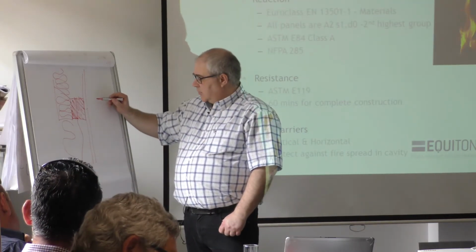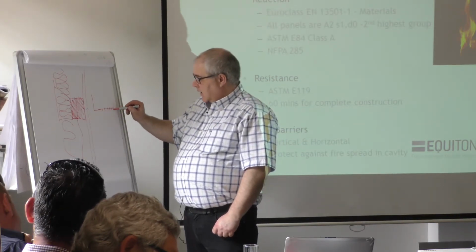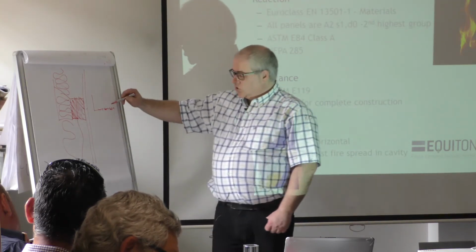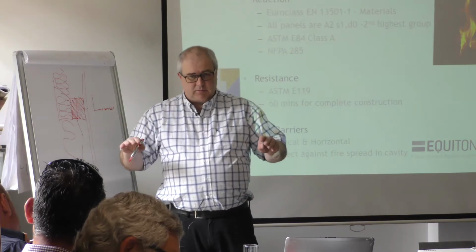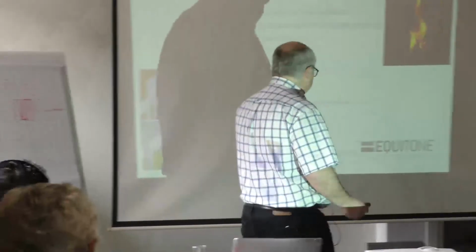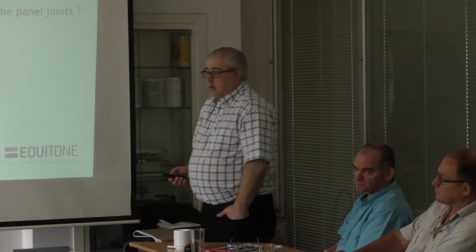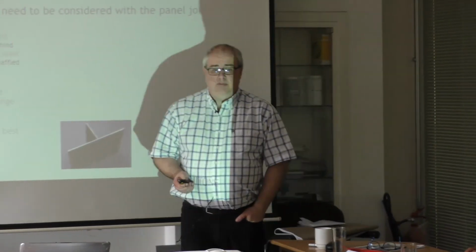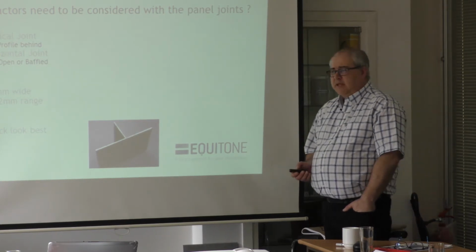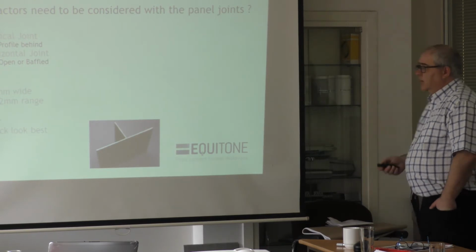There is another one available for bigger cavities, which is a metal strip with holes in it. And that's the same. It's got intermittent paint on it. It allows ventilation and drainage, and then when the fire happens, it seals up. Okay? So they're available for such constructions. Sorry, what was that name again? Promat is the company. Yeah, they're our sister company here. I can't remember, I think RSB is the code for it, but once you talk to someone about it, they should know about it.